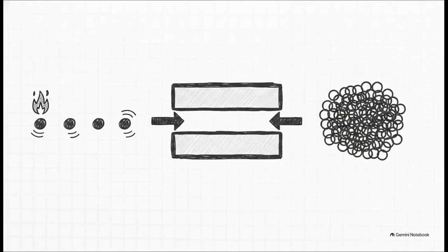And these carefully calculated band gaps, they aren't static. They're actually highly sensitive to their environment. For example, if the temperature increases, the extra thermal energy causes the atoms in the crystal to vibrate more, which increases the interatomic spacing. This actually causes the energy band gap to shrink. Plus, if we heavily dope the semiconductor, meaning we intentionally add a massive amount of physical impurities, the wave functions start to overlap, which also shrinks the band gap. And this brilliantly illustrates how thermal energy and dense physical impurities actually physically alter the semiconductor's capabilities. The environment literally manipulates the quantum particles.